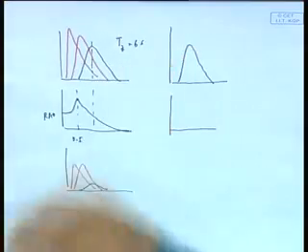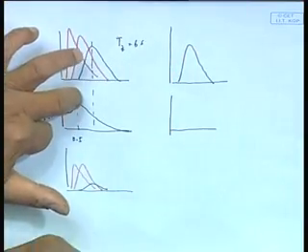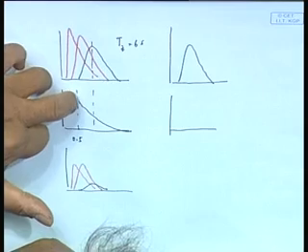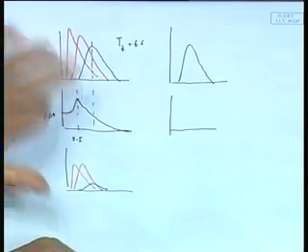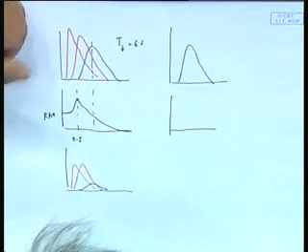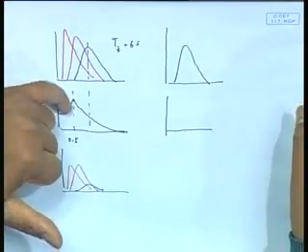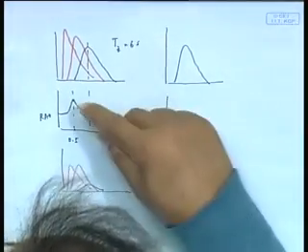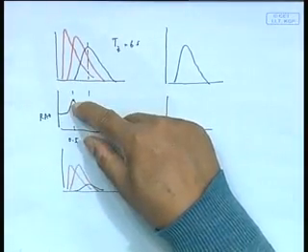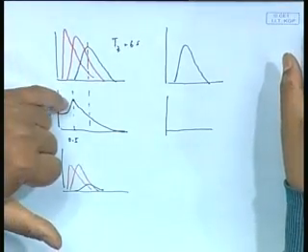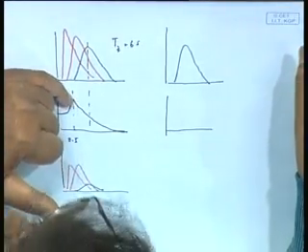Now, I will also want to tell that this is why we talked about this natural period so importantly. You see this natural period, this peak is a natural period, this is the peak at which my response is maximum. Okay. Now, if I have a wave at which my response is maximum, then I am going to have a very bad motion. All right. How much it should be?